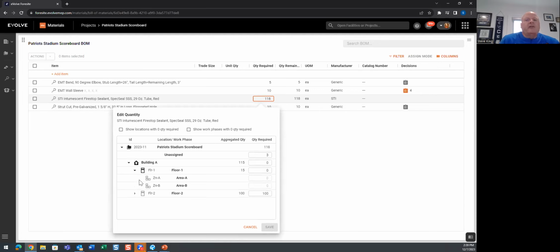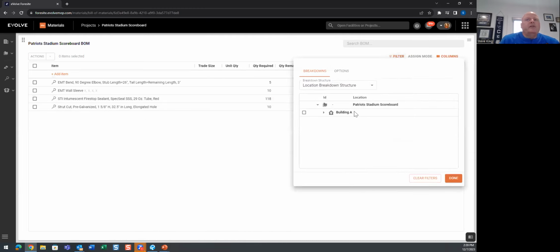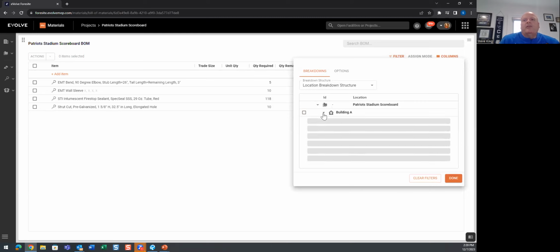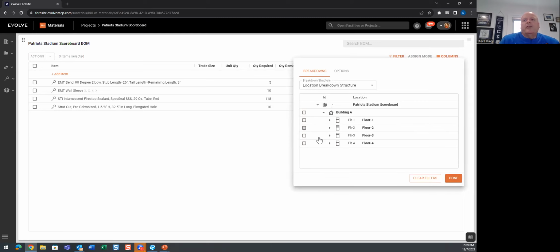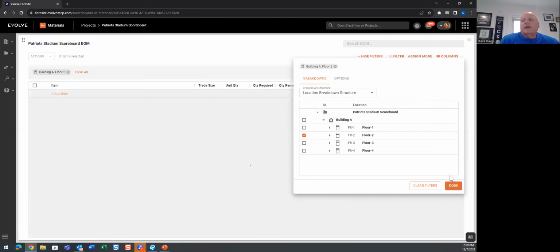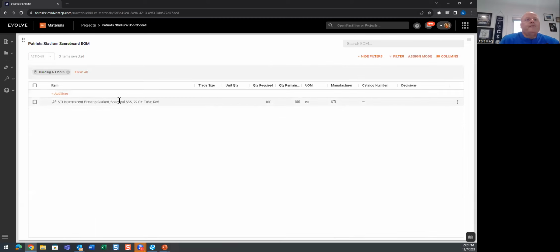So here, if I come back to them, you can see now that I've got those quantities in those locations. I can then filter for those locations, pick up that location breakdown structure and say, okay, show me what I have on floor 2. No problem.